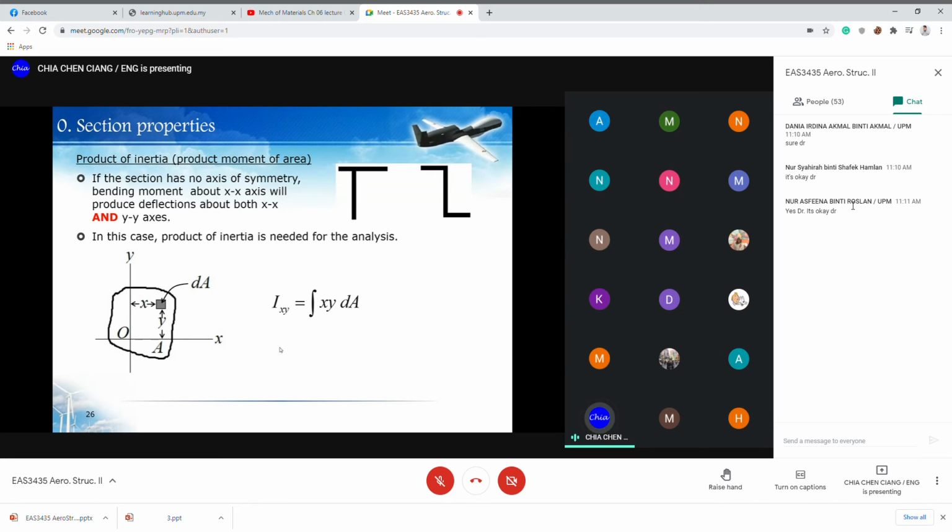It will not in any circumstance bend sideways. Can you follow? Yes. Okay, so for this circular tube, the IXY is 0 because there's no coupling between the axes X and Y. Whatever you apply to the X, you get it in the X. There will be no output in the Y-axis. No coupling. They are not affecting one another.